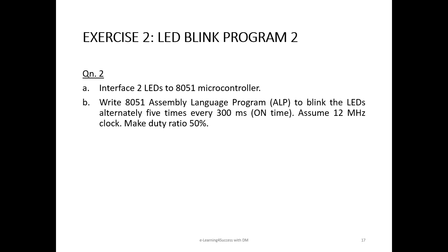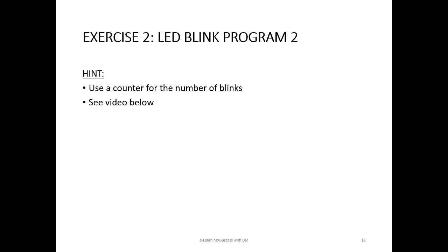Now the exercise question that I am going to give you is to interface two LEDs to the 8051 microcontroller. Then write the 8051 assembly language program to blink the LEDs alternately 5 times every 300 millisecond. The 300 millisecond given should be taken as the LED on duration only. You can assume a 12 MHz clock and 50% duty ratio. The hint that I can give you is that you need a counter for counting the number of blinks.